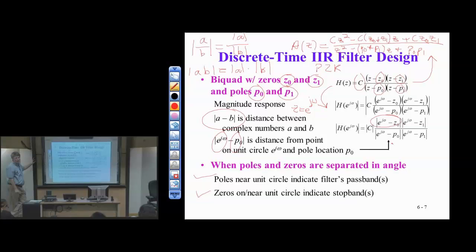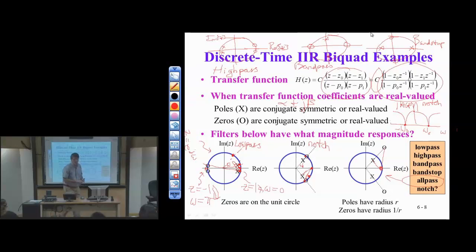That's it. And you now have a biquad. So now you know the difference equation to implement the biquad for any input signal. Again, demos coming. Any questions on this? It's pretty important. So you don't have to run software to design your filter necessarily.